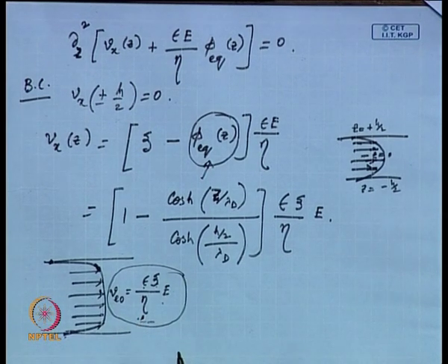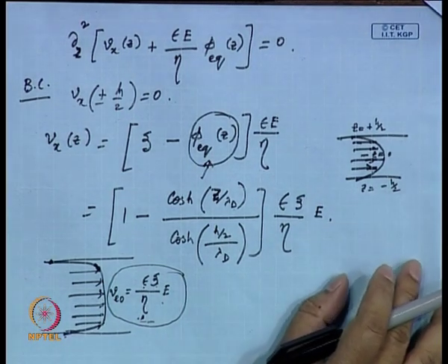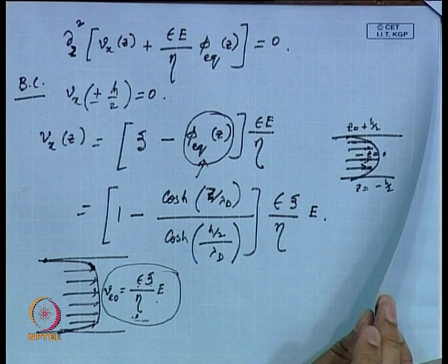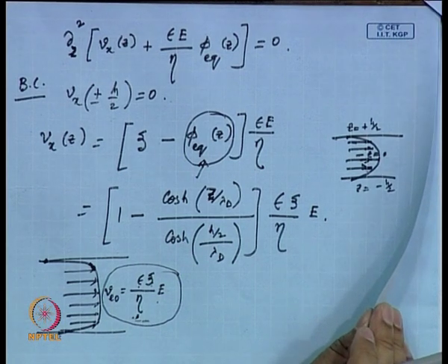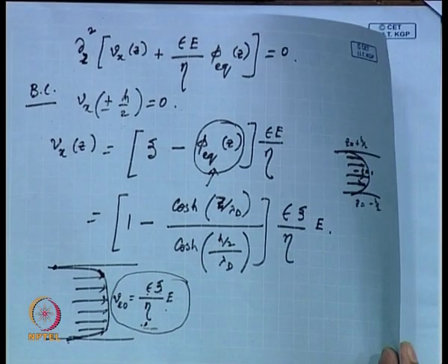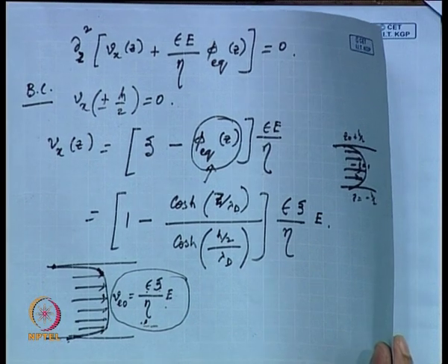If somebody wants to find out what would be the electroosmotic velocity under certain situation, he needs to use this formula. And if he is asked to draw precisely what the profile would be, then he needs to resort to this expression. All right, so this is what you have as far as this electroosmotic velocity is concerned.